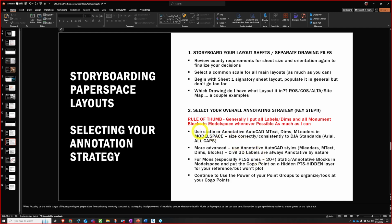You might not be as good with annotative objects as you are in AutoCAD. They're a little bit of a pain. Civil 3D objects are annotative inherently. They're smarter. But I'm talking MText, dimensions, MLeaders, and blocks. There's a little more caressing to get those to be annotative. If you're not quite comfortable doing that yet, get with myself or Hugh or some of the others that have done those. There's a few more things to tweak with them.